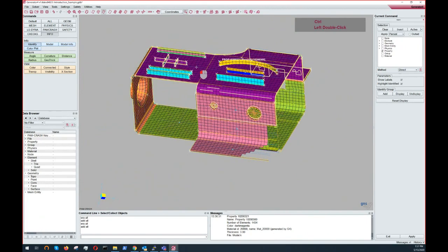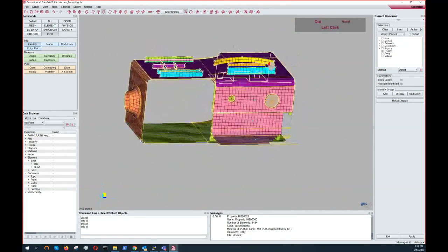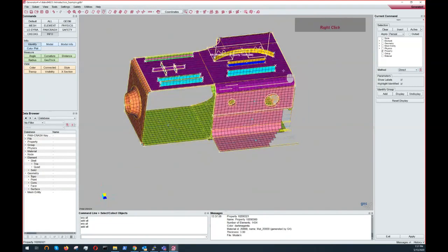This is interesting in identify, to get them unidentified right away, because it's like a toggle. Or in other commands like rotate, if you are not sure how much you want to rotate some part, you can keep going and you don't have to reselect everything.